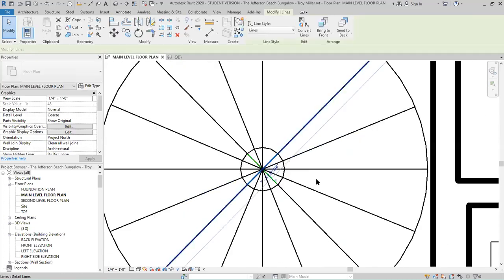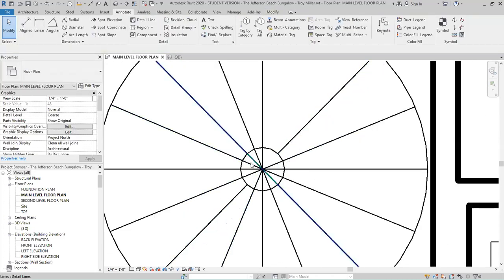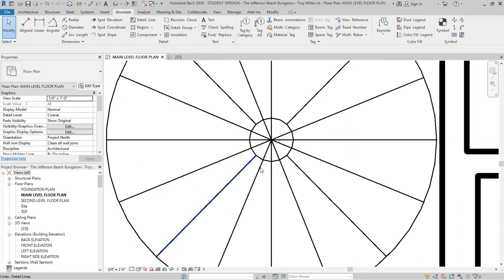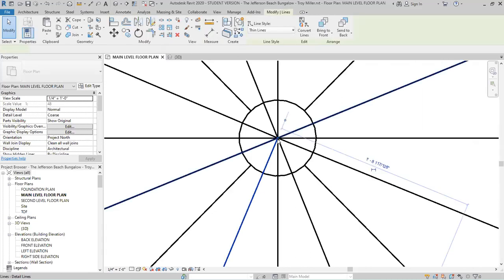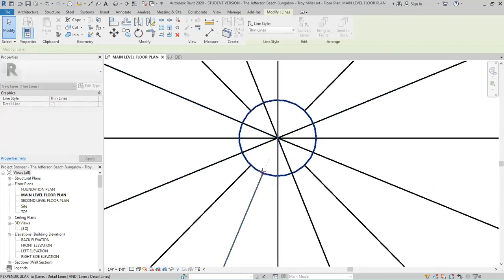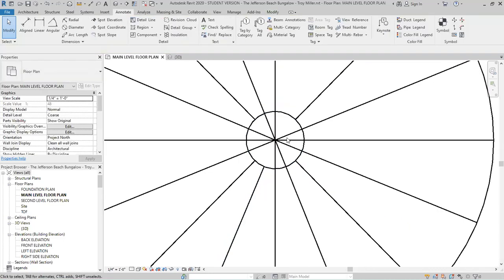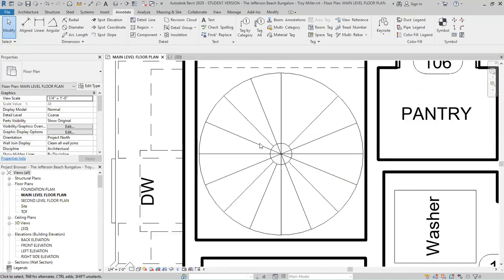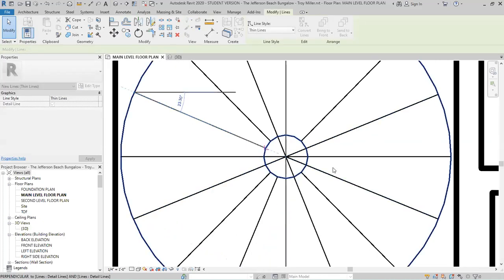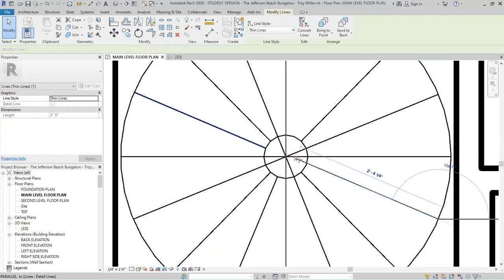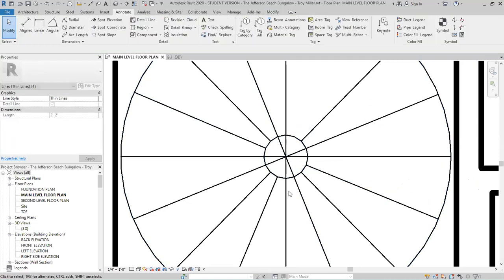I'm going to get rid of my two original construction lines right here. Now, because we didn't extend that spoke up, we didn't need to, I'm going to select there and just bring that back. Make sure you try to keep snapped into that location. Looks like we've got a couple here that are also broken, so I can take those back.